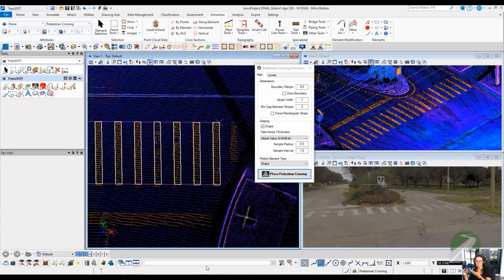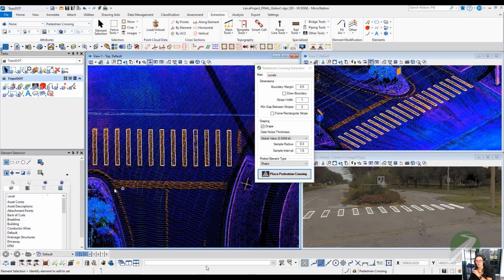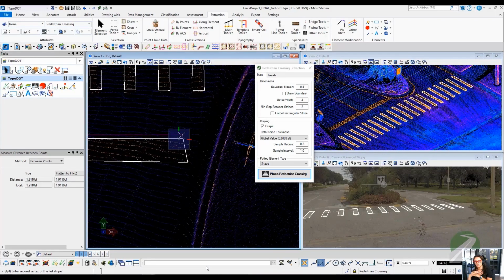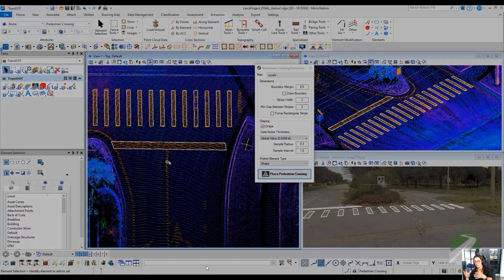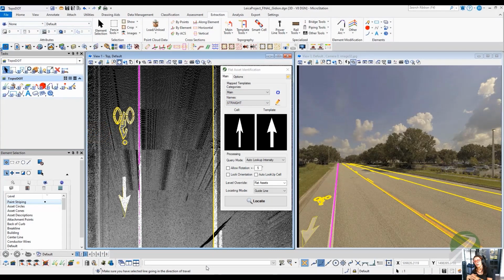Maybe you don't need the paint stripes, but you can use that information to create a center line down the road and an alignment down the road, or even just to create a line that is going to help you extract other features. In that same fashion, anything that has intensity values that we can isolate, anything that's being painted on our road, has specific tools for feature extraction.